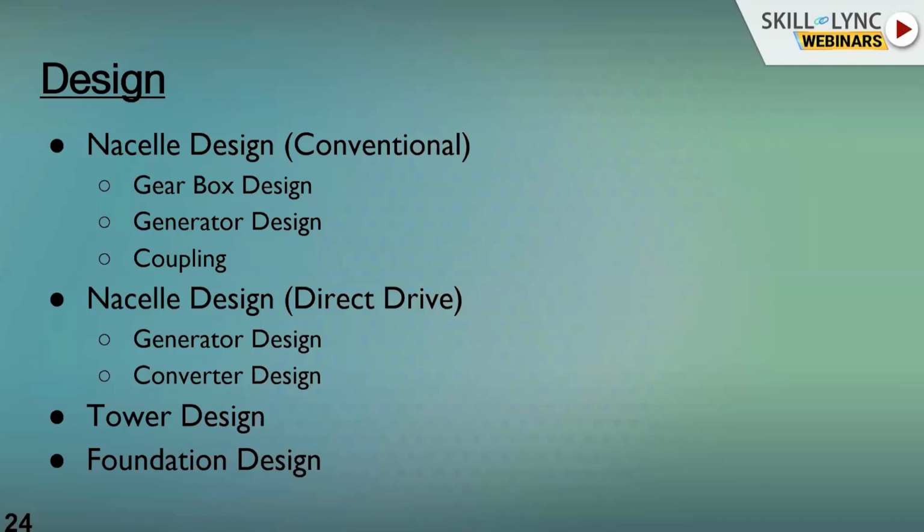So various technologies are available. Nowadays a lot of manufacturers are using concrete towers and concrete to steel hybrid towers, a combination of concrete and steel. Up to 50 or 60 meters height, they will go for concrete, and above that they will place a steel tower. In steel towers, lattice is the old one for smaller turbines. Tubular is for higher megawatts, and concrete to tubular and lattice to tubular combinations are available. This is only to reduce the cost and to achieve higher heights.